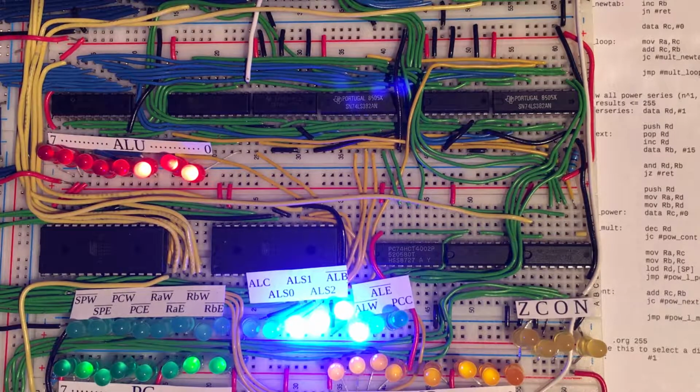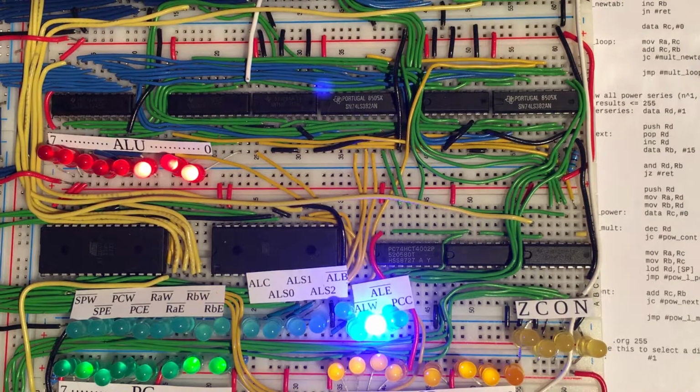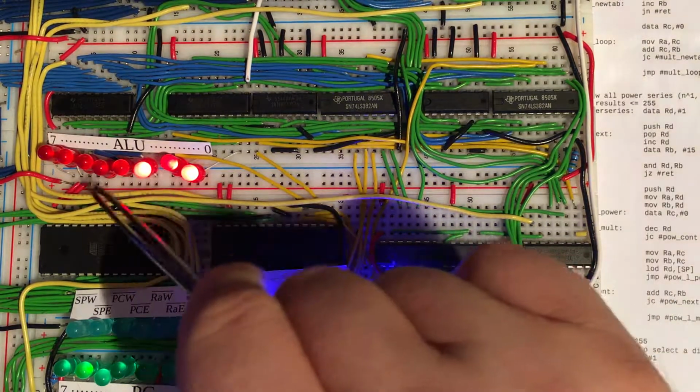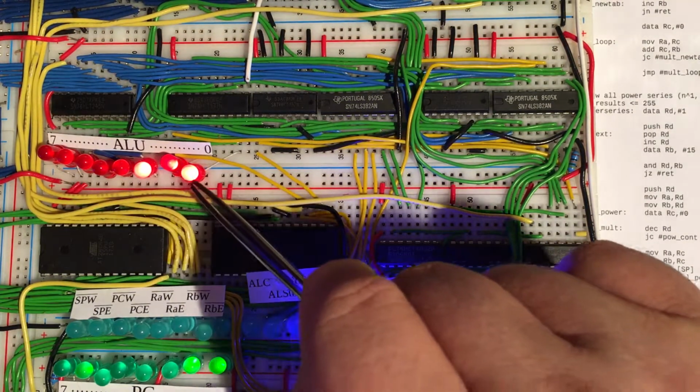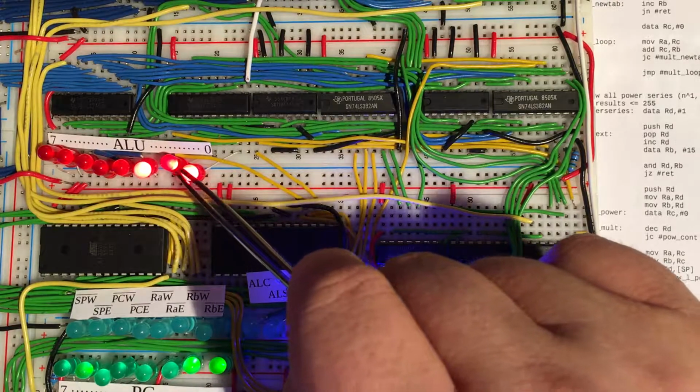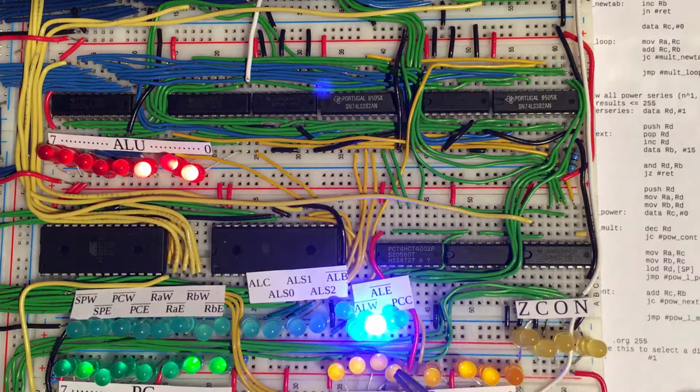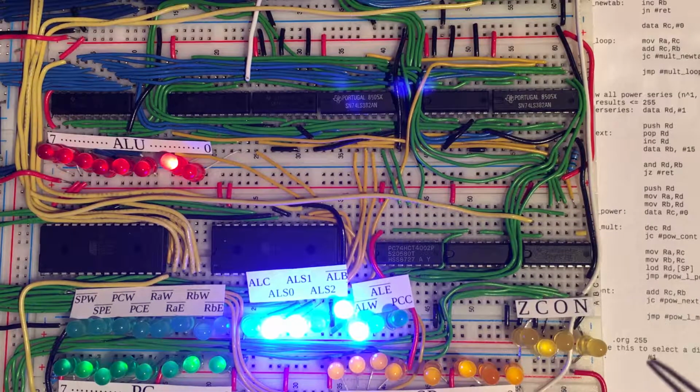And so that's what will happen on the next rising clock edge. And then once again, that value, which as we said would remain 7, is now being output back onto the bus, and that's going back into the D register. Now the computer is in fact about to execute this add instruction as a final example. So it's going to add once again the B register, and this time to the C register, and write the result in the C register.